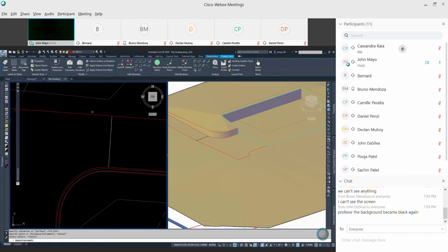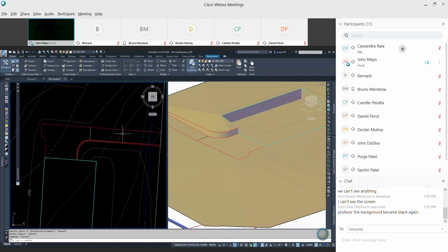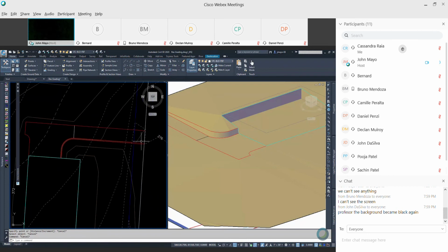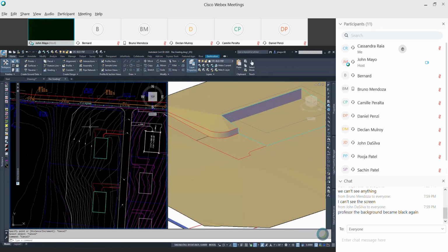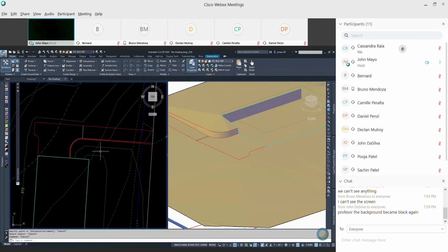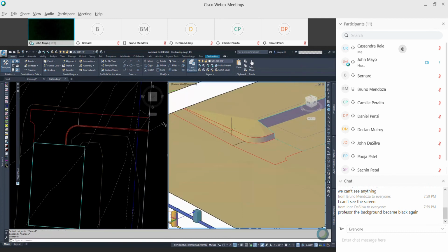All right, so let's look at our contour. Ooh, much better, right? Still flowing a little bit off that way, that's fine. Actually, it's flowing out that way, which is even better, because we would be collecting the stormwater runoff from this house somewhere in the back here, and we can swale that water away, but it's running away from the building, and that is your primary concern here. You can shorten this driveway down if you want.